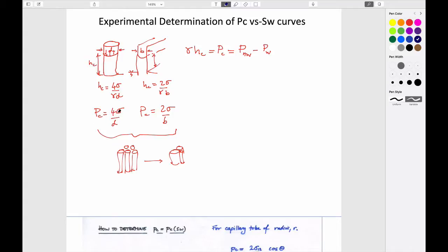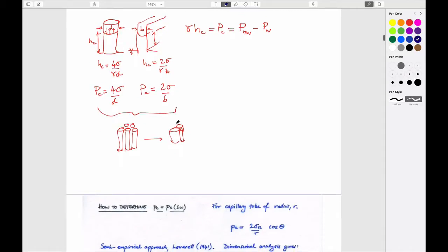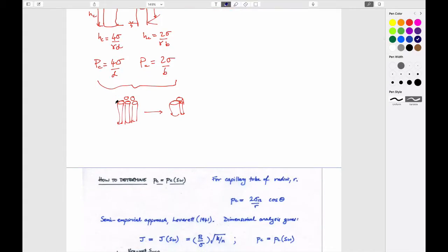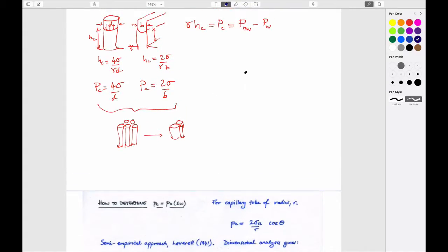They say something about entry pressures, but they're not completely useful to us because we want to know what the ensemble behavior is. And if we want that ensemble behavior, then what we can use is this capillary pressure versus saturation curve. And this capillary pressure versus saturation curve will always look like this. I can probably draw it better here without all the abstractions.